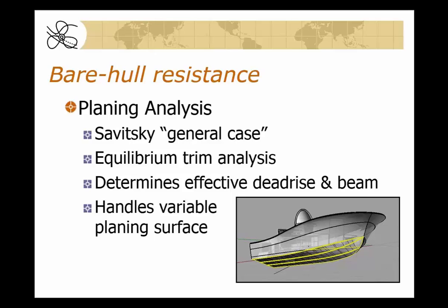This is the Savitsky general case that we're using, which is an equilibrium trim analysis. Those of you who may be familiar with Savitsky may recognize that there are two different approaches. There's what's called the simple case, and then there's what's called the general case. The simple case puts all of the forces and moments through the center of gravity. The general case incorporates lift and drag or thrust vectors from different components, and that's the methodology that we have employed here.